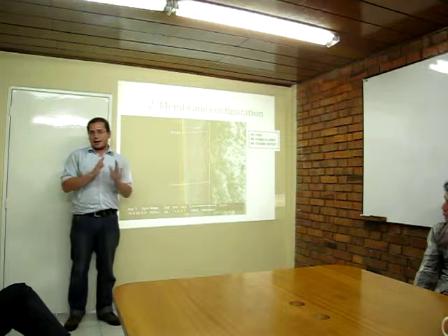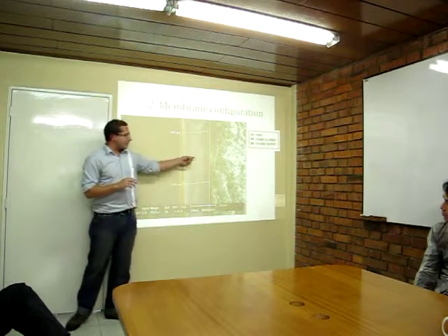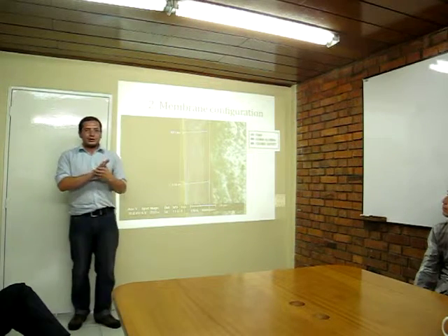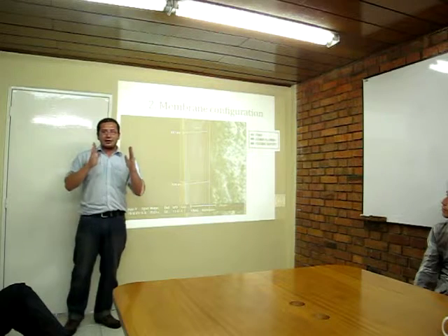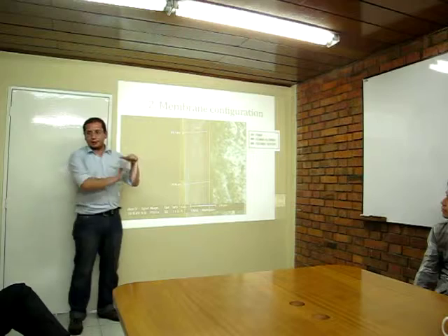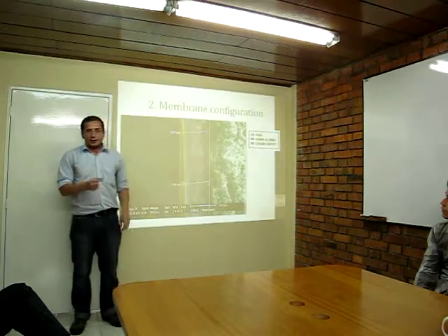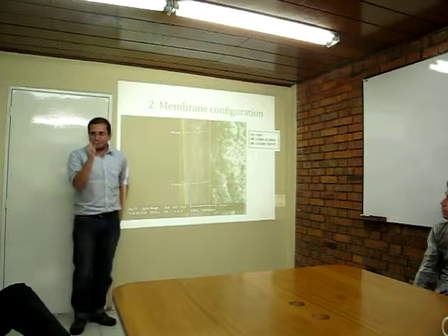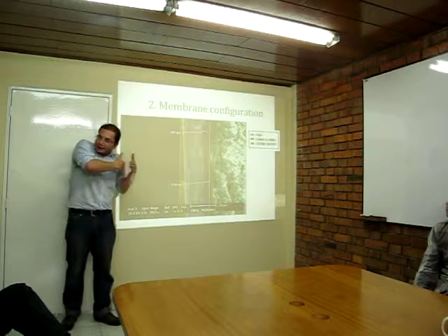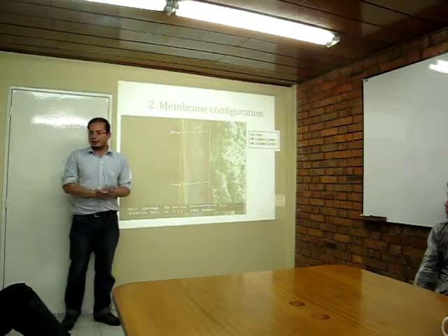This is a behavior of the membrane. But if you don't put this layer, you have a problem, because the membrane tries to expand inside the ceramic support, and this is a problem of flux. But if you put this layer of gamma alumina, the pores are very small, and the membrane can expand in these pores. For that reason it is gamma alumina.